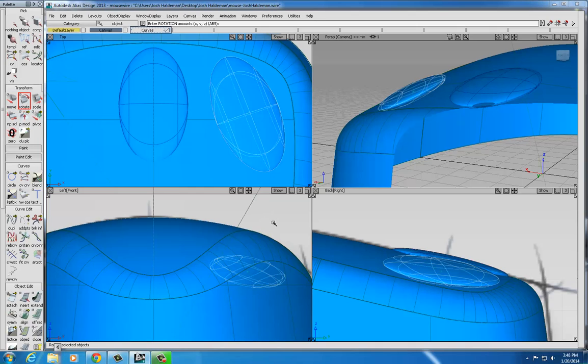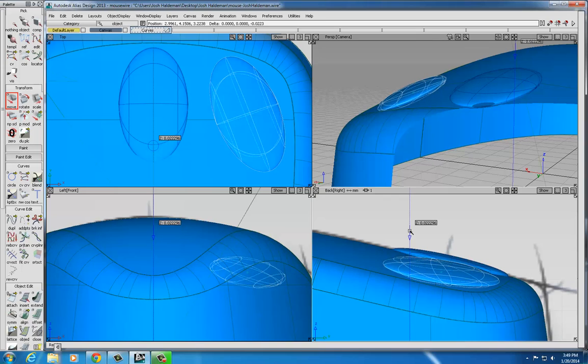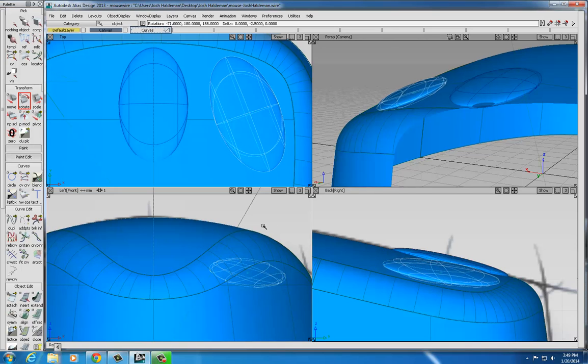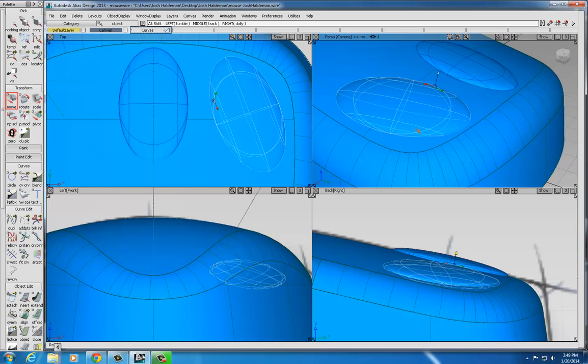When you do the rotation, left to right, back and forth, just keep checking it to make sure that you have the object halfway below. So in this case, I'm going to go around the Y again a little bit. Let's go this way just a touch, and then let's go back down a bit. It looks like it needs to go down more. That's about as much as I'm going to get without losing it on the other side. So let's rotate again, again around the Y, and move it down some more. And it looks like we're pretty close there.